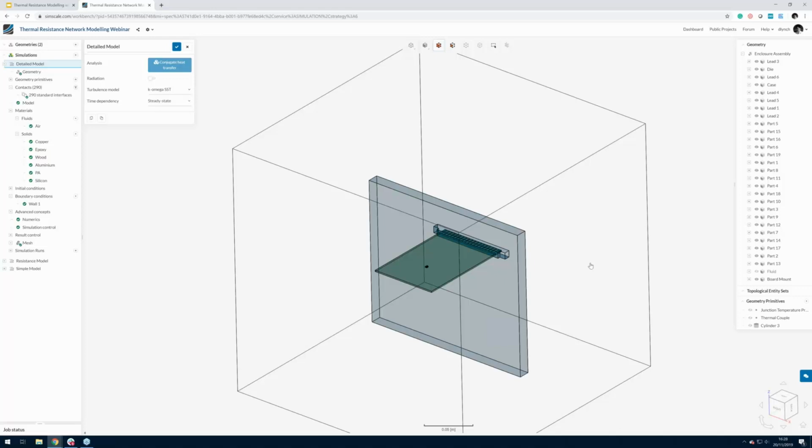By validating your calculations, you make sure that you're getting comparable results between your detailed model and your resistance model, and therefore you can go and use it in whatever scenario you actually deem fit to use it. So you could then from here go on to include this into a complex assembly of all these different components, including say 100 of these components, and you could use the same definition for all of those 100 of the same components.